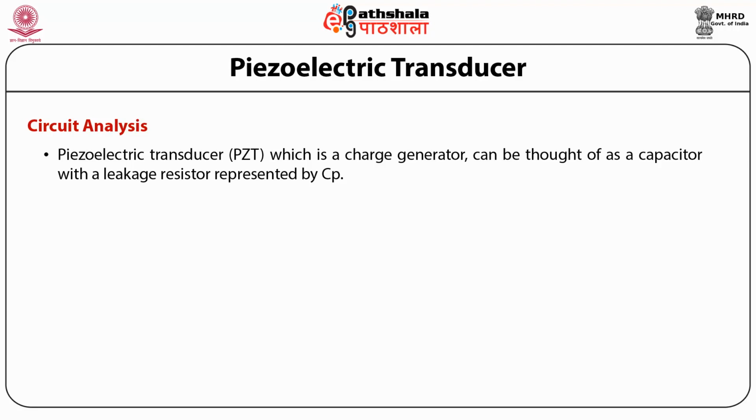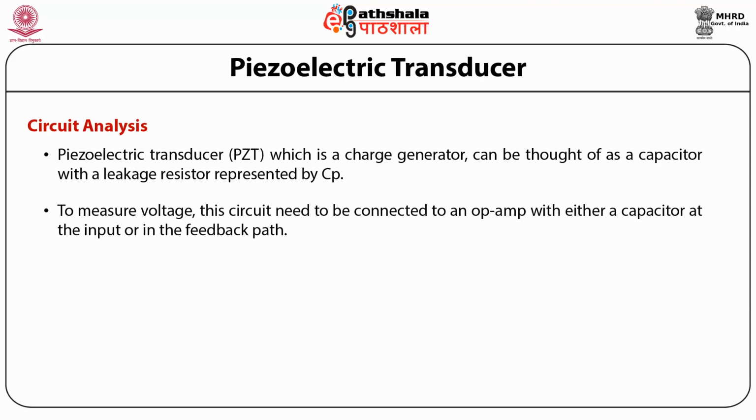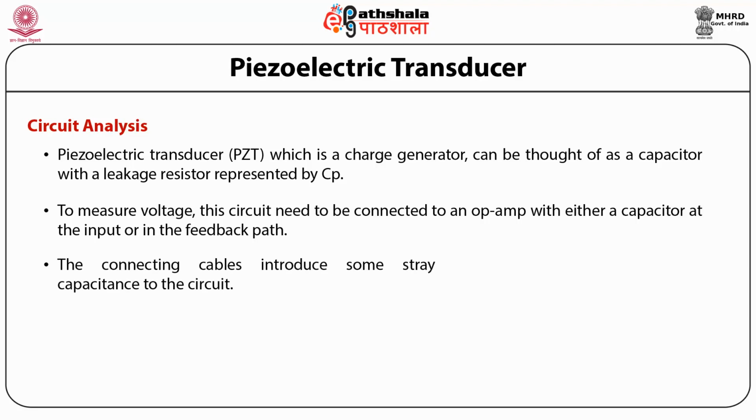So let us now discuss the circuit analysis of the piezoelectric transducer. The piezoelectric transducer, PZT, which is a charge generator, can be thought of as a capacitor Cp with a leakage resistor. In order to measure the voltage, this circuit needs to be connected to an op-amp with either a capacitor at the input or in the feedback path. The connecting cables introduce some stray capacitance to the circuit.